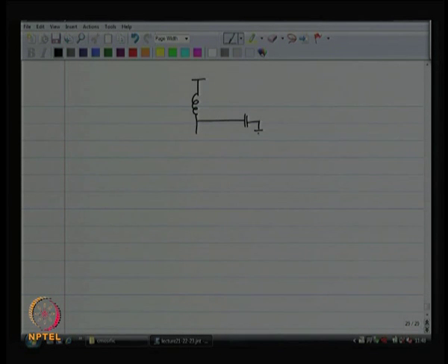This is my load, this is my cascode device over here, this is small signal ground as far as the cascode is concerned, and as far as my input device is concerned, I have got an inductor connected to my input voltage source directly. I have thrown out that capacitor because hopefully it is a large capacitor which is going to make it a short.